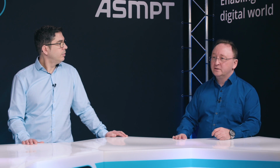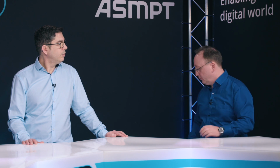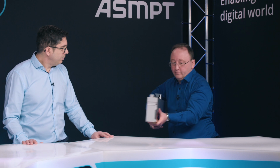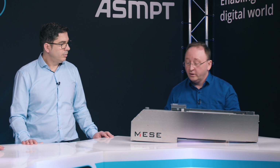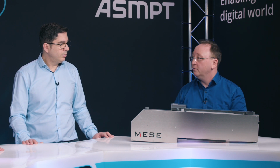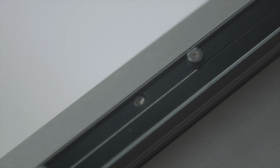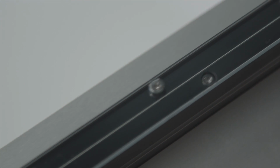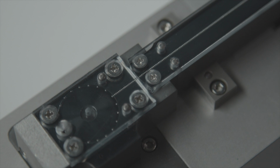And another feeder type which is quite often requested now are feeders for non-packed components, which is often called bowl or bulk feeder. And I have today an example with me. So this is a feeder from the company Mese. As I said, it's for non-packed components, in this case for small balls, ball diameter from around 0.2 to 0.8 millimeter. And the material of the balls can be different. This can be lead material. This can be, of course, also steel material. And we have also a customer which is feeding ceramic balls with this feeder to the machine.